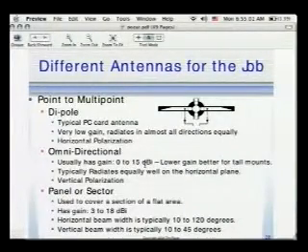So think of a flashlight. When you have it unfocused and the beam is really spread, it's kind of a dim beam, but as you focus the beam, where it becomes more and more narrow, it becomes brighter and brighter. You've actually increased the gain in that direction. So an omnidirectional can have gain by taking the energy that would be going straight up and straight down and squeezing it out towards the horizon.